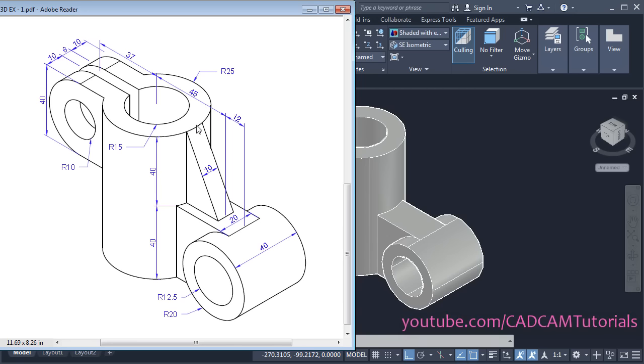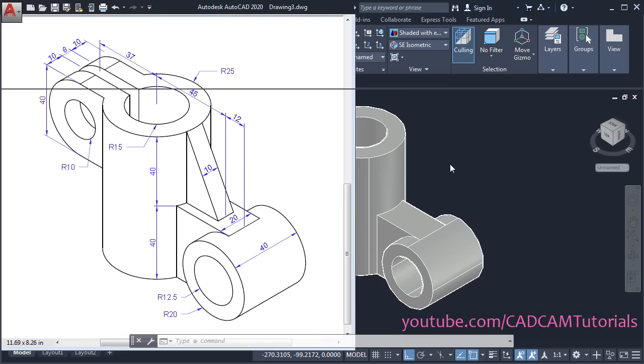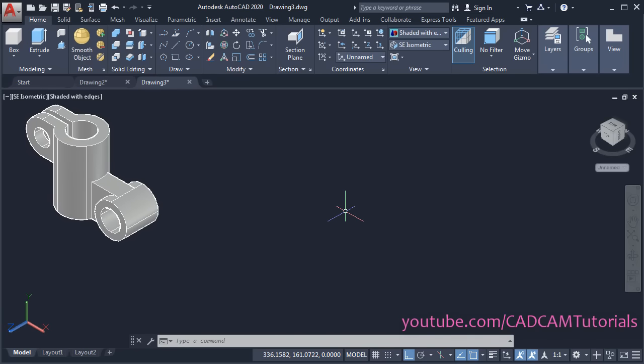Now this rib is a complicated feature. We will need this curvature here. So to create this rib accurately, we will have to use loft command. For that loft, we will create some sketches. At first we will create this bottom shape. Now we want to create those shape horizontal. Therefore click here and select top so that XY will be horizontal.